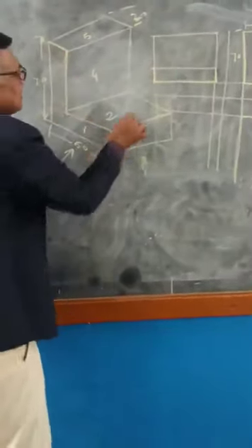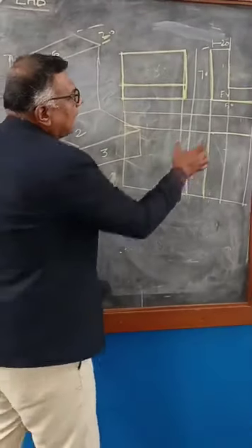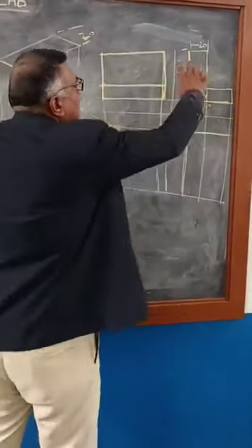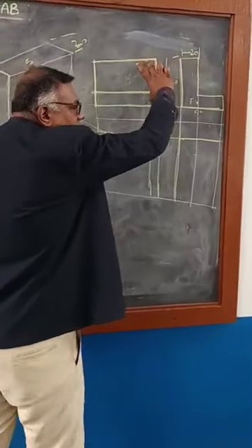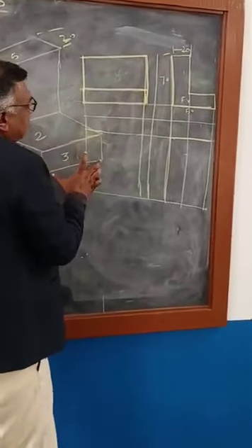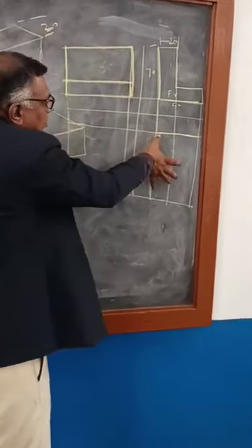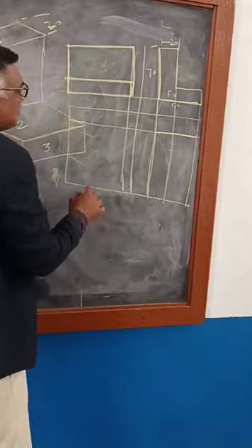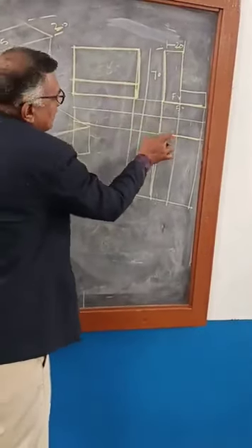So from this we can conclude that the front view length and the top view length will be the same. Then the front view height and the side view height will be the same. So already you know this value of 50 or 70, whatever it may be. Then you should know that this horizontal line length is over and height is over. How will you take this height?